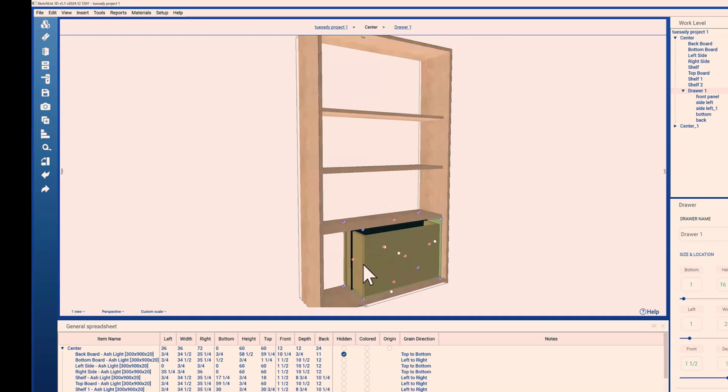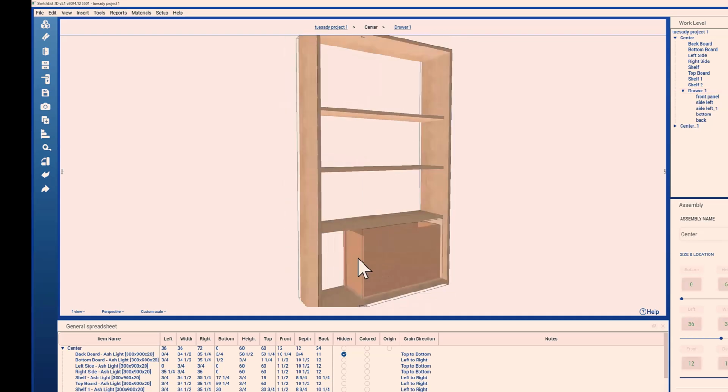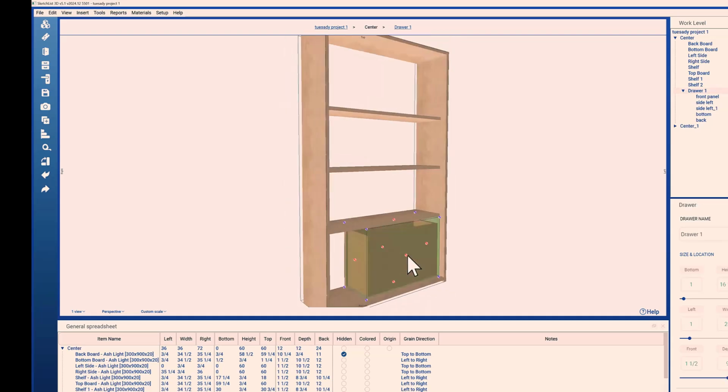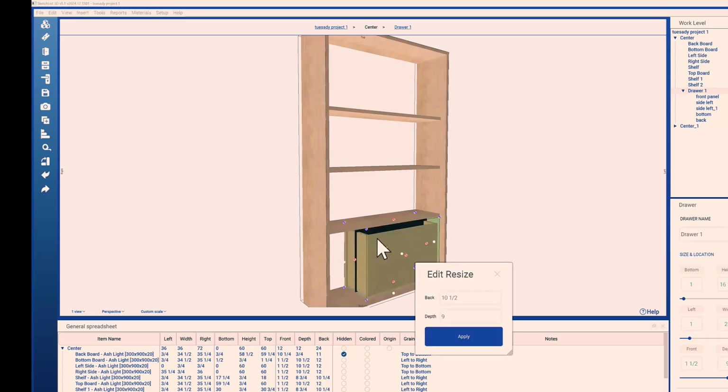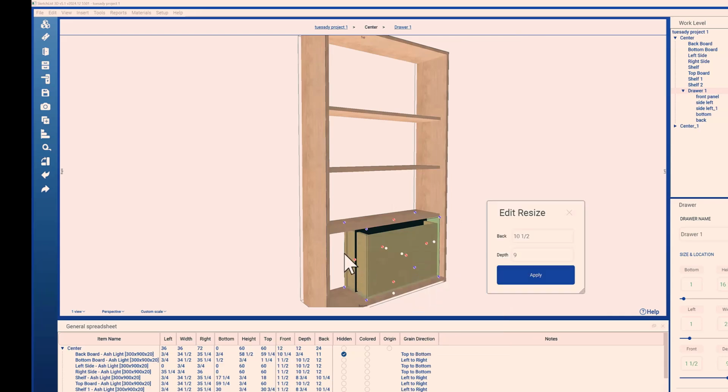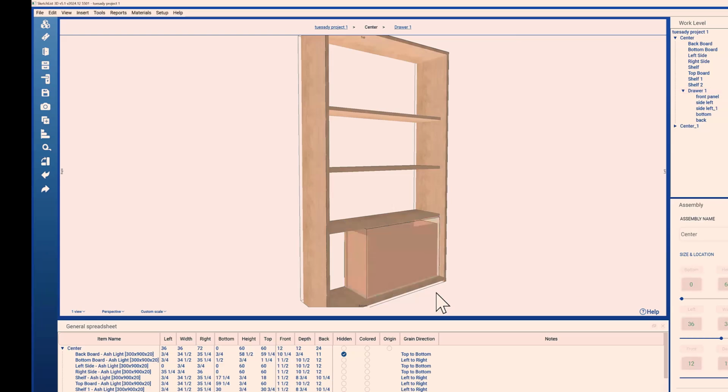What it does when you do that kind of change is, let me do it again. You see that black box there? The rule is that anything that's in front of the box, the cutting plane, is going to stay because I'm moving backwards. Anything that's behind the black box is going to be moved, and anything that's touched by the cutting plane is going to have those 2 inches added to it. Want me to do it again?